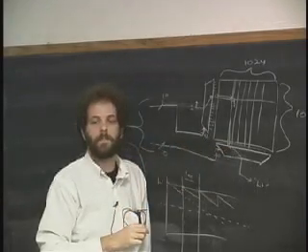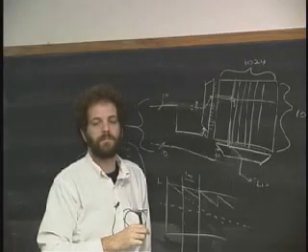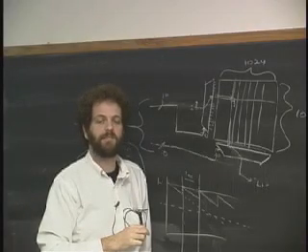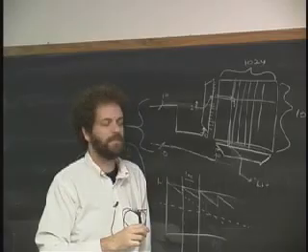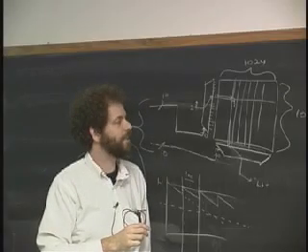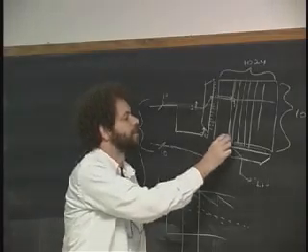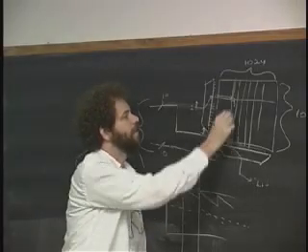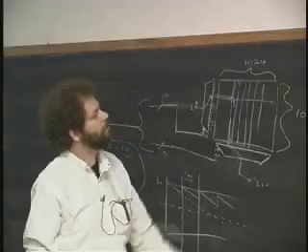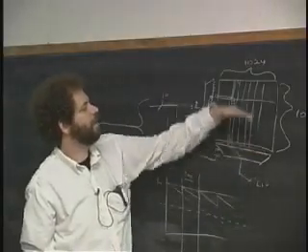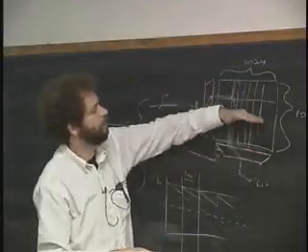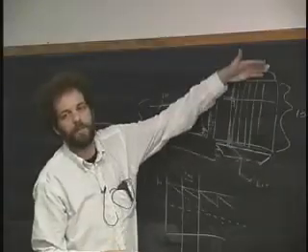Does the amplifier know the address from which it was coming, and amplify by a different amount? That's an excellent question. Oh, well, that guy was farther away, so he needs to be boosted by a greater amount? That's absolutely right, and the answer is yes. Okay, so they actually do that. They actually know that there's a scaling law between what happens down here and what happens way up here. In fact, they usually have two sets of amplifiers. They have one down here and they have one up here. This one gets it from this half of the chip down. This one gets it from this half of the chip up.